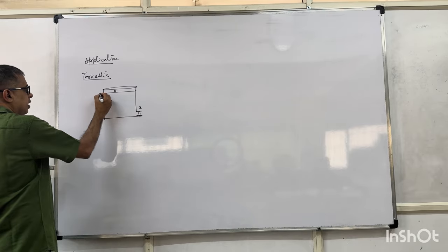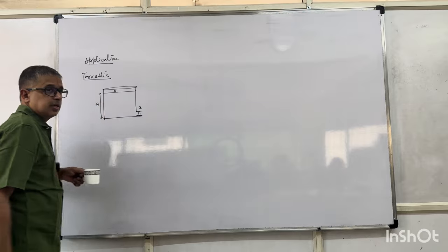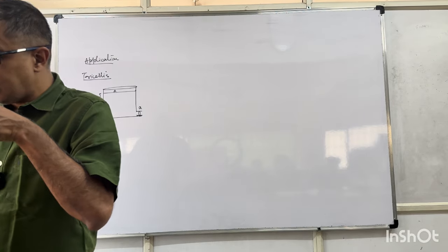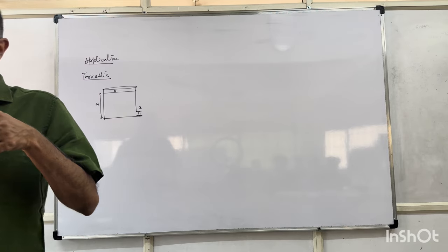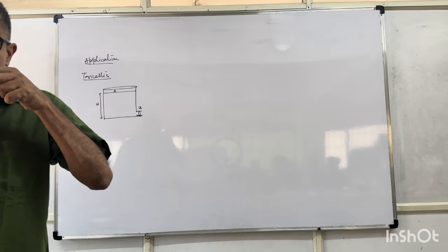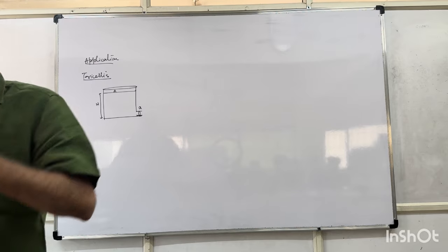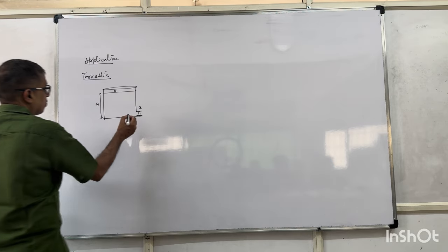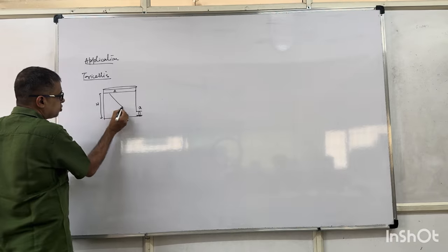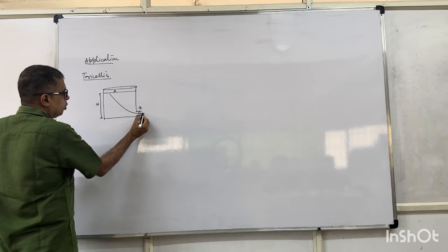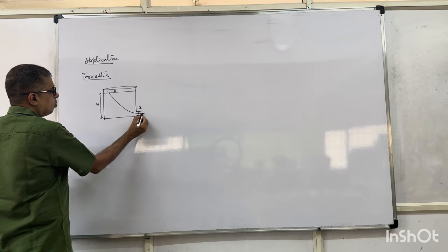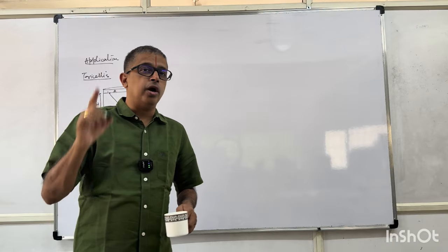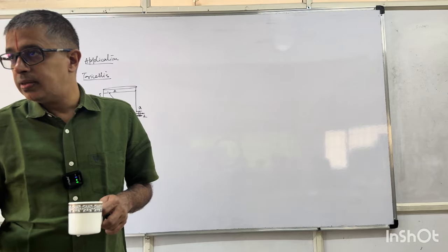This height of the liquid is capital H. I am interested in the force exerted and I am interested in the velocity of the fluid flux, the velocity with which fluid is coming out. Now, if you take a streamline like this, you apply it to point 1 and point 2. You will apply Bernoulli's equation to 2 points on the same streamline.